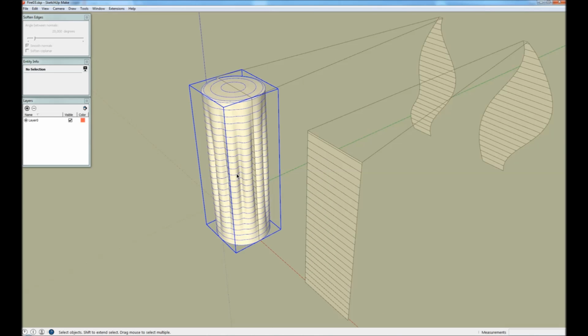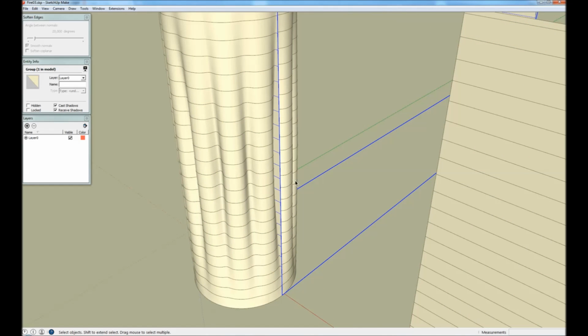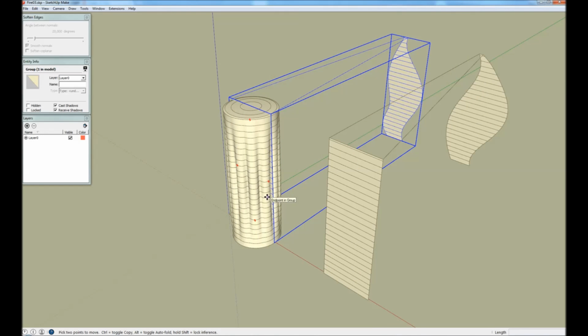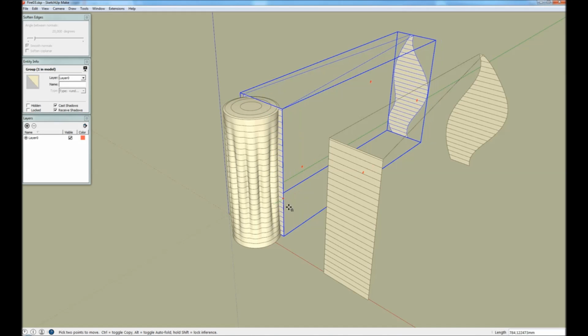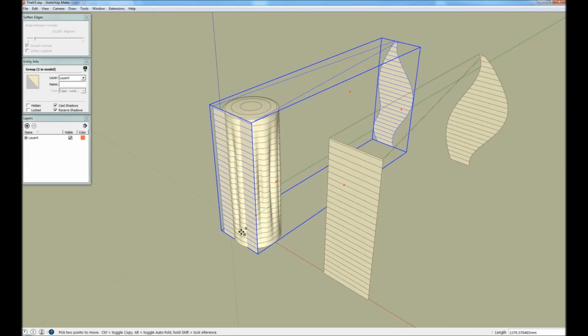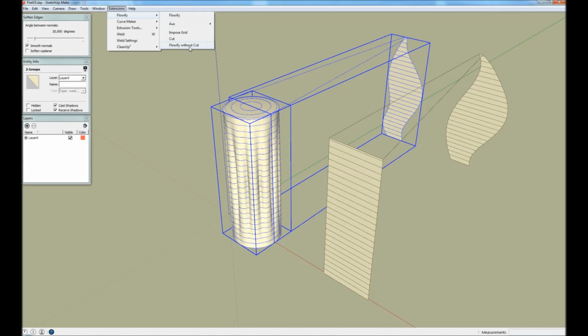So we can now Flowify this without cut, and the reason is that the only thing cut does in Flowify is to move this projection grid like a grinder through the geometry. But as you can see, this grinding would in this case not introduce any new geometry. So this source geometry already contains all vertices needed for a proper Flowify. So we're going to select Flowify without cut, and it is also much faster because intersect is the slowest part of the extension.